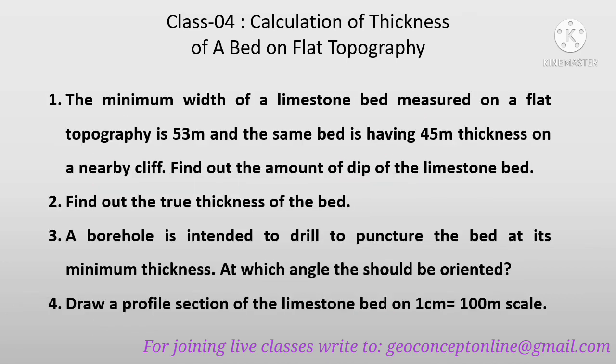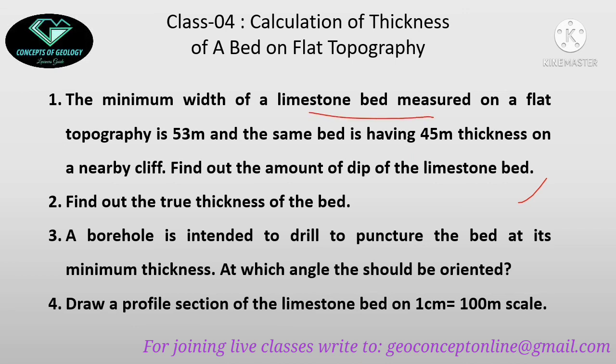Fine. So this is the problem given for today. The minimum width of a limestone bed which is measured on a flat topography is 53 meters. The same bed has 45 meters thickness on a nearby cliff. So that means if I do a borehole, I have the thickness 45 meters. This is the apparent thickness. The bed is definitely inclined here. When I am measuring the outcrop on a flat topography, this is 53 meters.